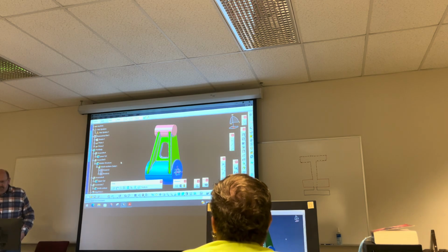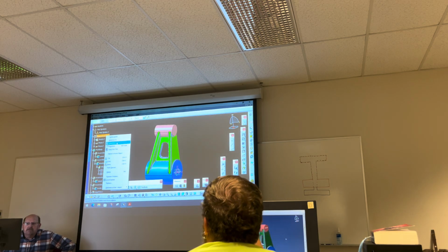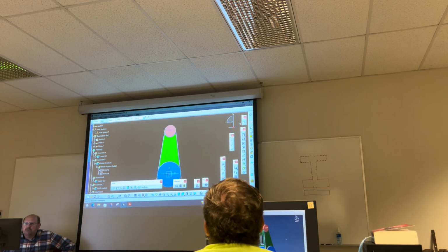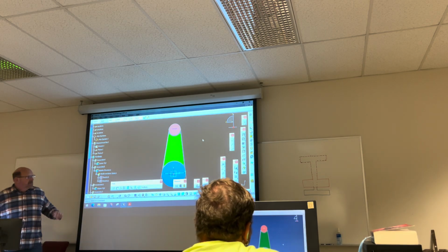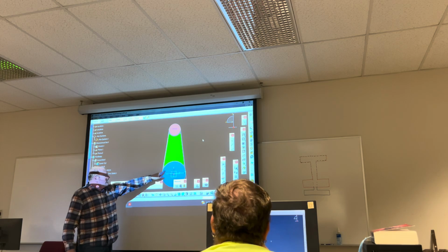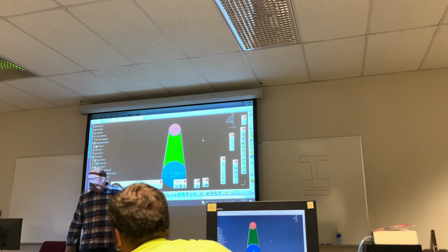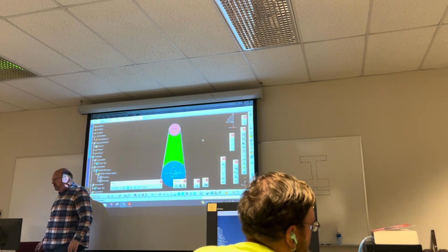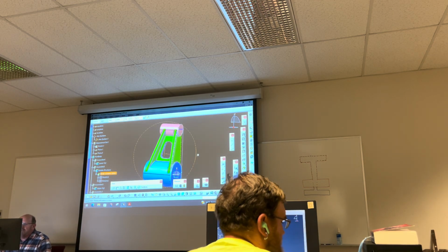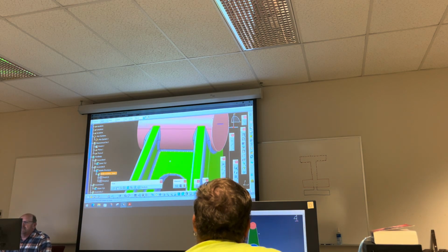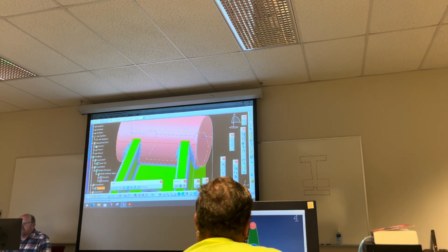And the biggest thing is this setup from this view. Because if you don't do that to begin with, your chances aren't really good that you're gonna be tangent with any of the fillets. That's the other thing too, it'll build a fillet for you, but it comes over the top or the bottom. What I mean by that is, if you look, these end right here, because that's where it becomes tangent.